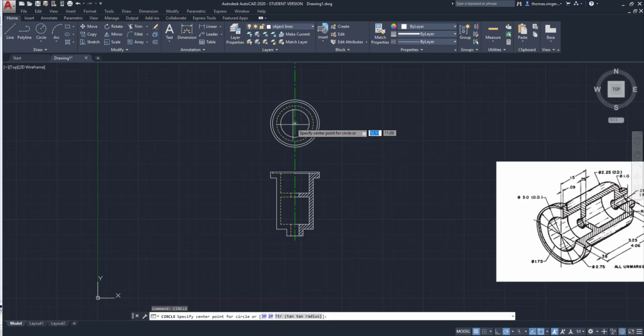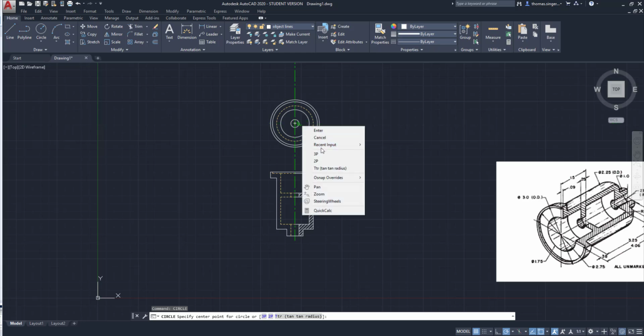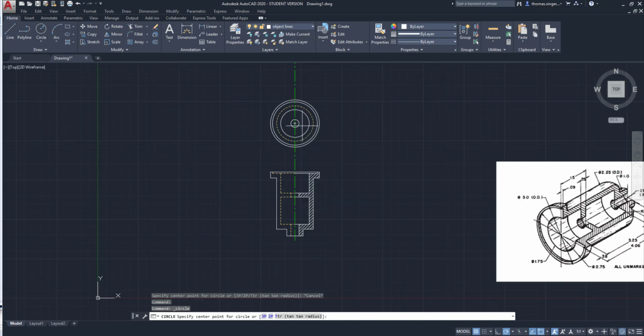And then we've got the hole on the inside, which is a 1/2 inch diameter. And then we've got the 1 inch diameter circle on the very bottom. Oops, got to pick circle to make that happen. Find the center, boom, drag it out. That can be 0.50 as a radius. That one also will be hidden because we can't see that section there on the bottom.